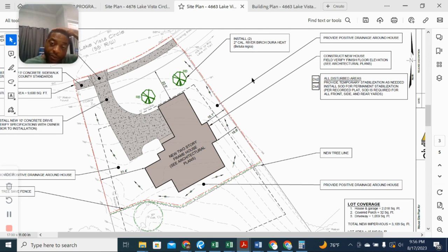You wouldn't want that happening if somebody's building by you. Okay, so the blue card, the erosion control, we deal with the silt fence, we deal with the construction exit pad, we deal with the tree save, okay? And then you make sure that you're able to address the disturbed area so you're keeping dirt and silt from leaving your site. You have to contain everything within your site. All right, so that is your lesson for today, and we will continue again.